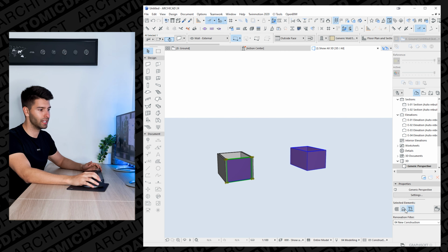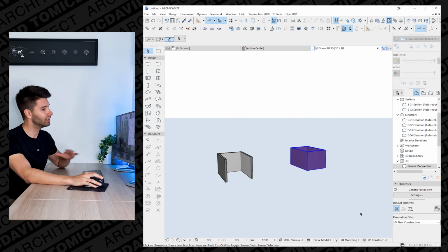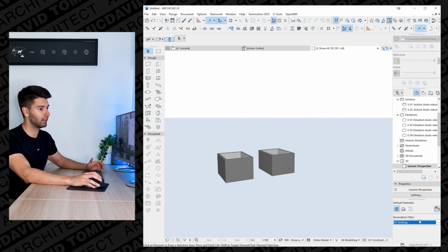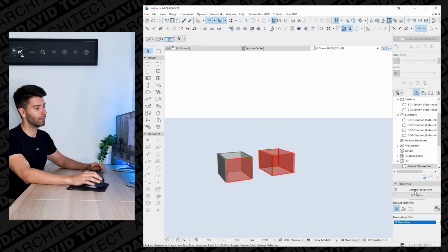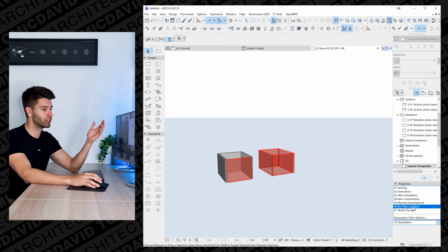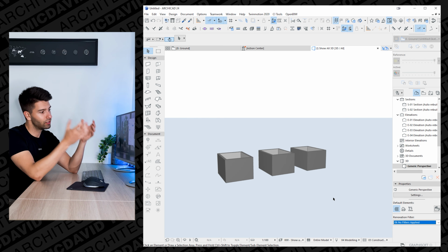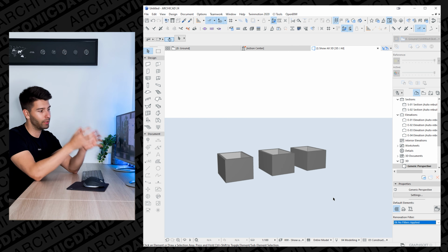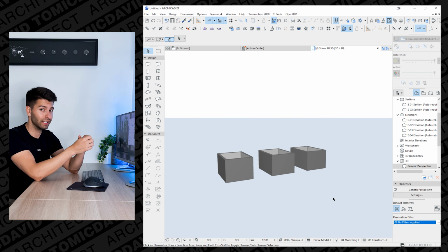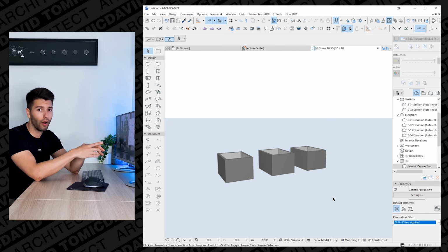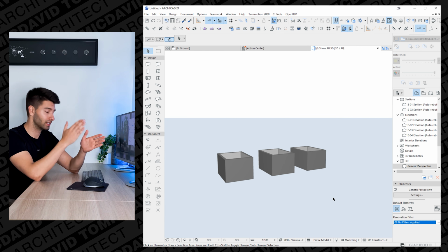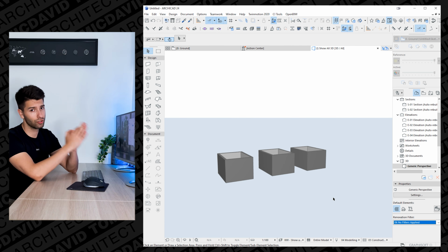The same principle applies for demolition. Let's knock that out. It's gone. You can't see it in new construction. If we move back to existing, it's there again. And then same principle, move to demolition, it's red. We know we're knocking it out, we know what we're doing. And finally, I'm just gonna go back to no filters applied to simply showcase the ease and ability of renovation filters. By clicking through some tabs, basically, we're changing our entire model in a matter of seconds. If you're not using renovation filters, man, you have been missing out for so long.